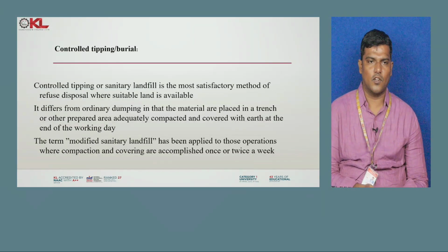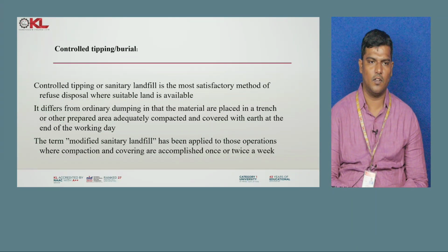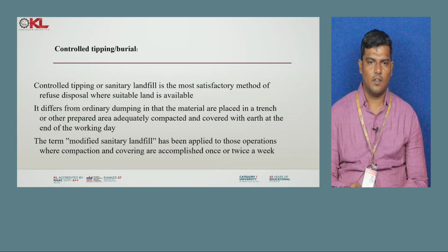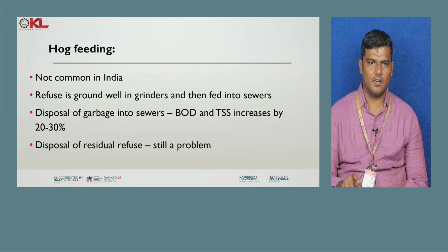Coming to the next one, controlled dumping, as I already explained. Controlled dumping or sanitary landfill is the most satisfactory method of refuse disposal where suitable land is available. It differs from ordinary dumping in that material is placed in a trench or other prepared area, adequately compacted and covered with earth at the end of the day. The term modified sanitary landfill has been applied to those operations where compaction and covering are accomplished once or twice in a week. So this is about controlled dumping and burial.